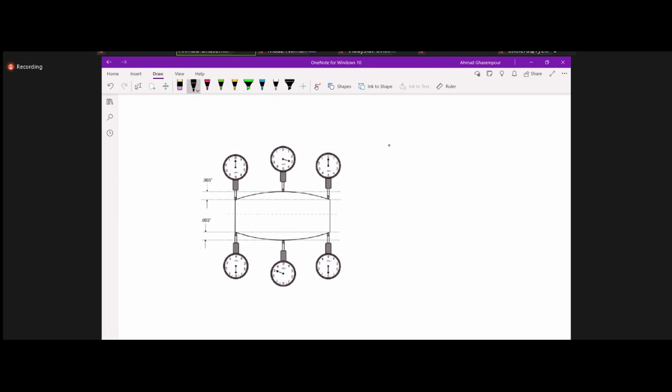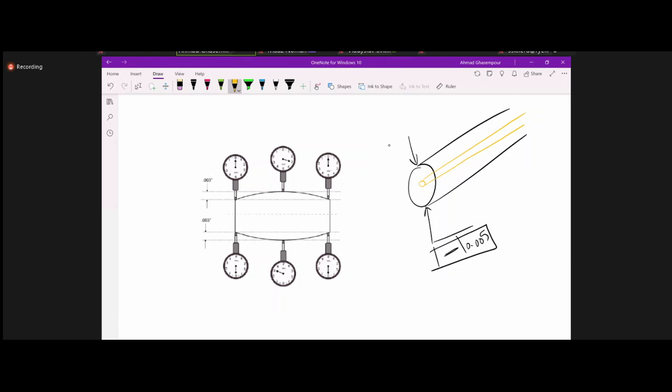This arrangement is useful if the straightness is applied to a feature of size and therefore applies to a derived center line, as we said. So if I want to find out whether the center of this cylindrical part is within the tolerance or not, this arrangement can be used, right? You have two dial indicators and move them together, and the difference between them is basically deviations.